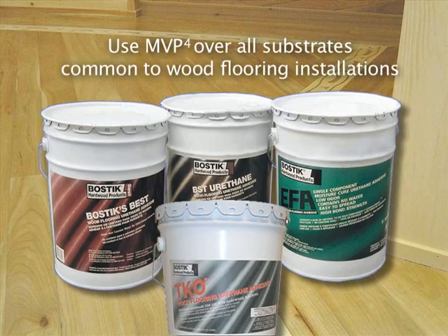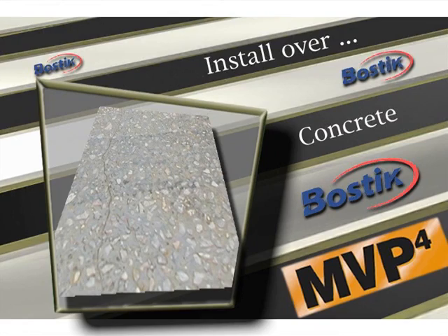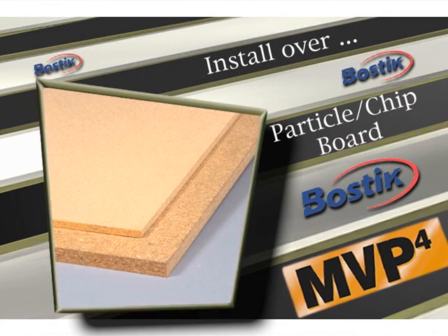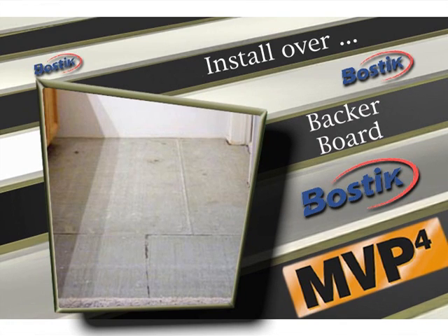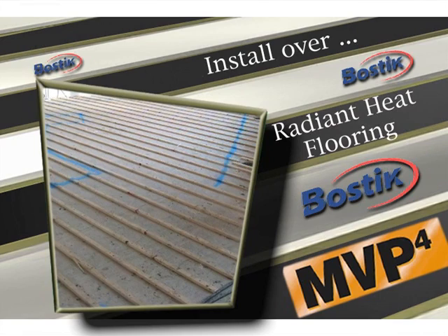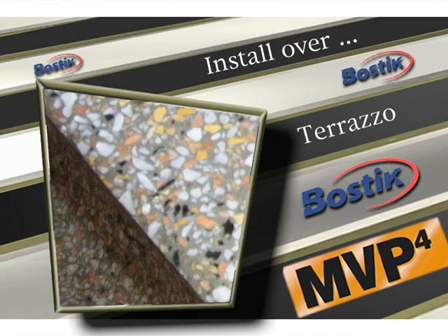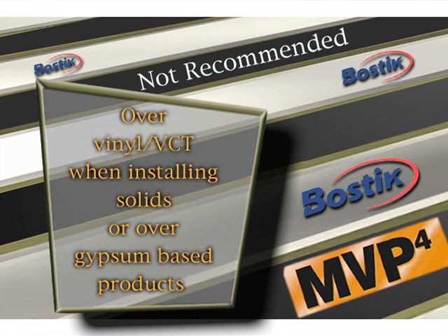MVP4 is designed to be used over all substrates common to wood flooring installations, including concrete, plywood, particle or underlayment grade chipboard, well-bonded vinyl, ceramic tile, cement backer board, cement patch underlayment, radiant heat flooring, or terrazzo. However, MVP4 is not recommended for use over vinyl VCT when installing solid wood flooring, nor is it recommended over gypsum-based products due to their innate limitations for moisture.